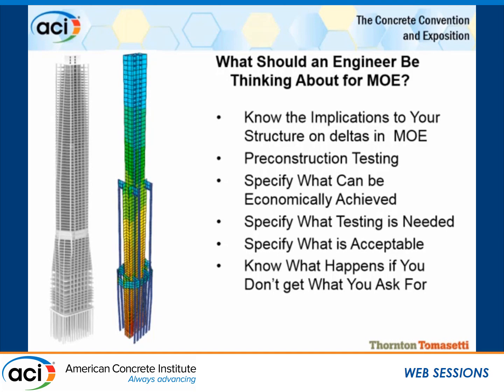Pre-construction testing is a must. To take risk out of the job, you have to do pre-construction testing. You shouldn't start the job and not have any idea whether you're going to hit your modulus under the construction conditions. So that's rule number one in my case. We should know what the conditions are where we're designing our project. Concrete is local, so we should know what can be achieved. We should not be specifying things that just cannot be achieved by the ready-mix suppliers and the contractors. That's where the conversation has to start.